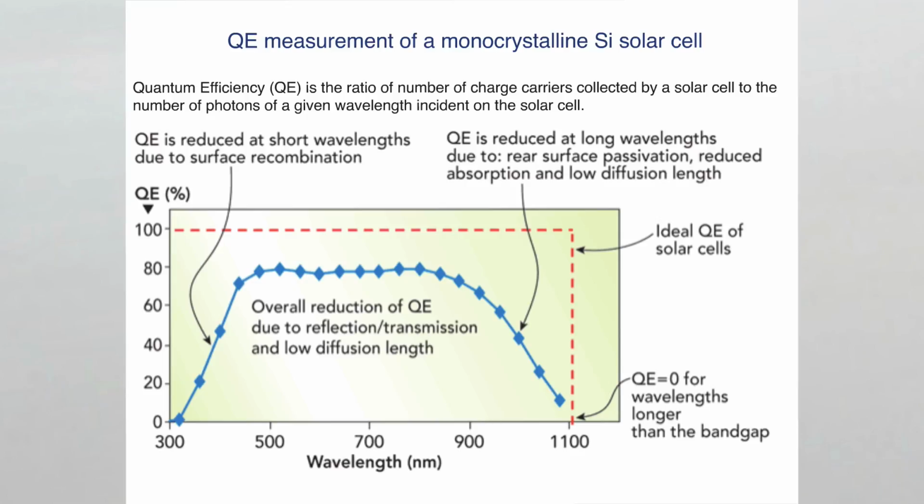What that means is that at the top of the solar cell, there are lots of crystal defects. And these UV photons will be absorbed very close to the top because they're very highly absorbed by the silicon. But those carriers will never make it out to the contacts. They'll just get recombined because of the defects at the top surface of the crystal. So that causes this problem.